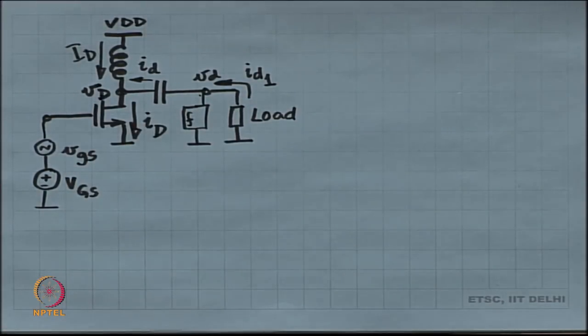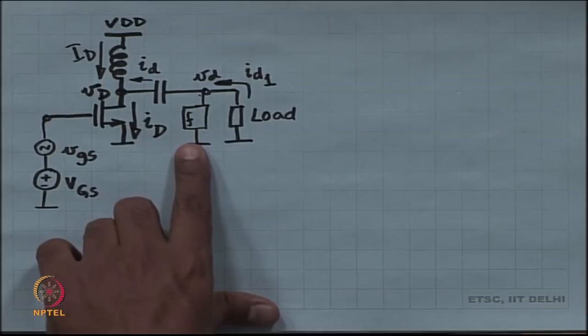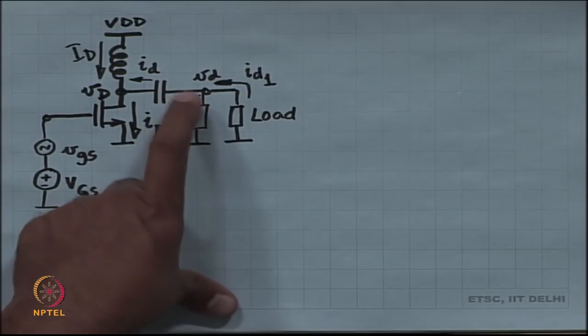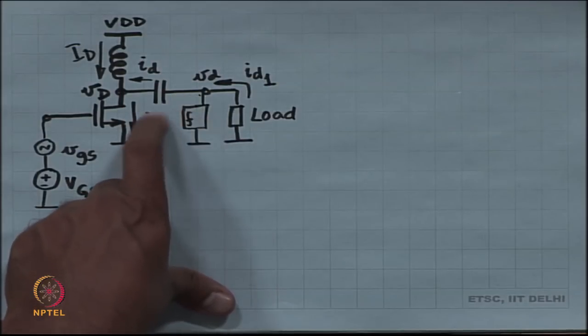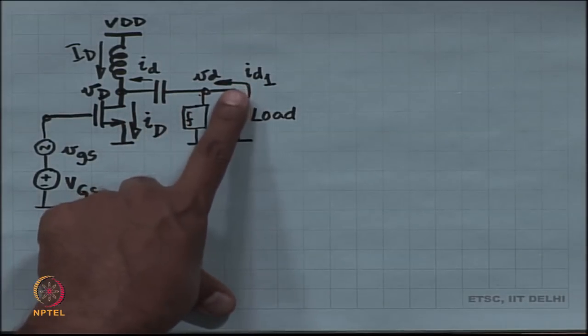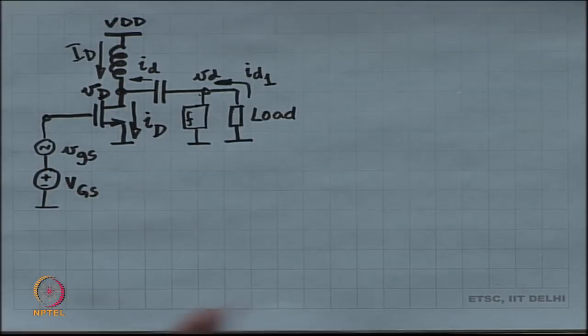Okay. So, the capacitor and the inductor are such that you can split the DC bias, the DC quantity of the voltage and the current, from the signal quantity of the voltage and the current. And this filter does a further splitting. The small signal i_d is filtered by this filter such that only the fundamental component goes into the load, all the other components go through the filter. So, this is the arrangement.